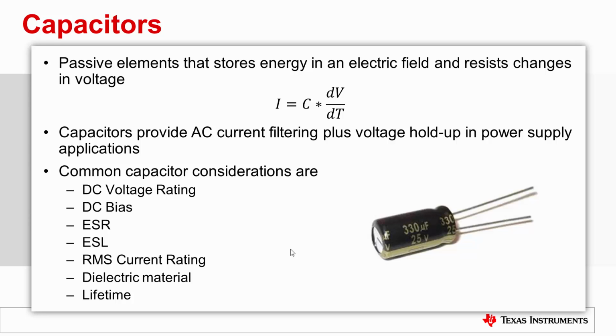Several types of capacitors, including tantalums and aluminum electrolytics, can be severely damaged if this voltage rating is exceeded. Pay attention to voltage excursions during transient events as well.